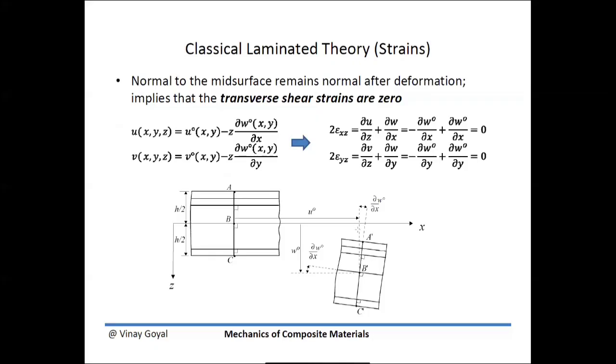So then what is going on next is that the plate deformation is driven by the second term here. If I look at the slope at any other point, say I have a slope of the derivative of w with respect to x of that plate, clearly the plate is tilted. And you can see here that this amount is the derivative of w with respect to x. And so that does contribute to deflection in the negative direction, and you can see that that's occurring right there.